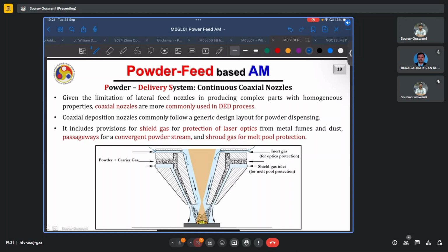That is, if there were the bounce back of any particles from the surface or the reflection of any laser energy back into the laser optics, or certain fumes will be generated here. And to prevent the entry of these fumes back into the optics chamber, the inert gas is purged through these channels.